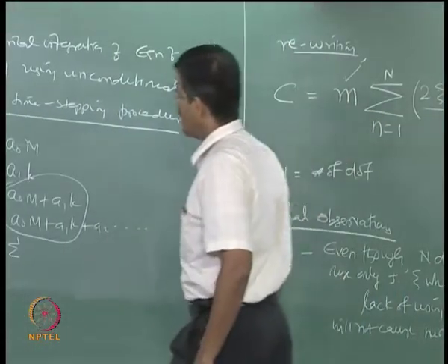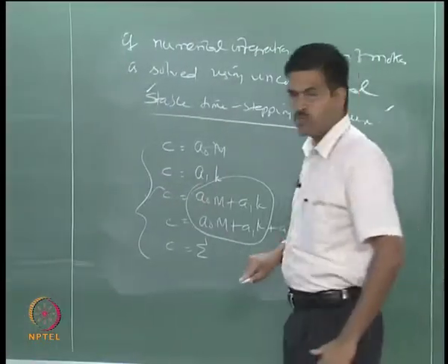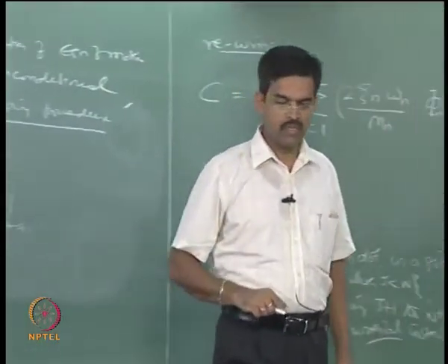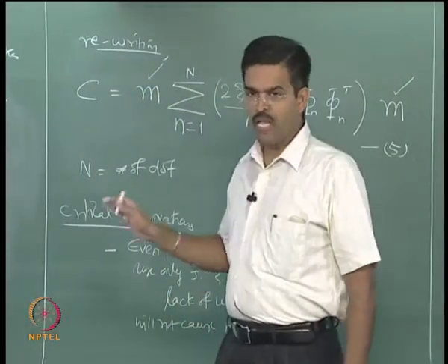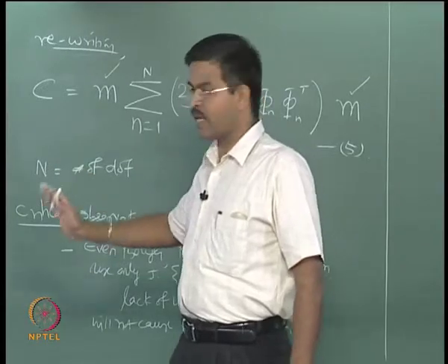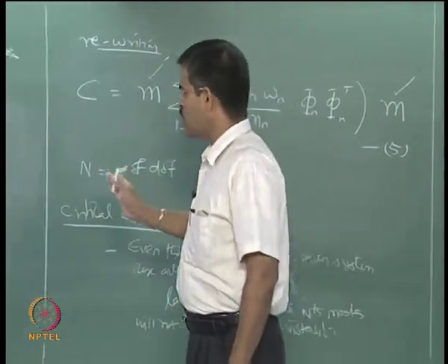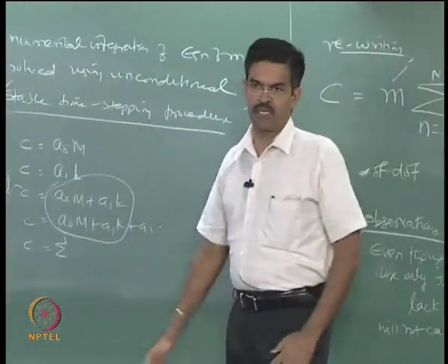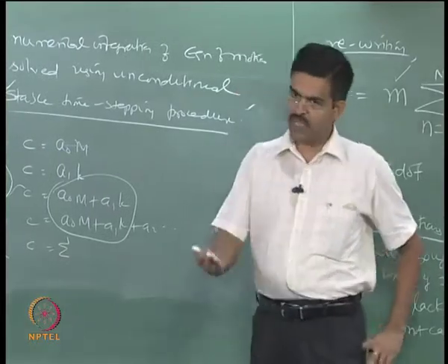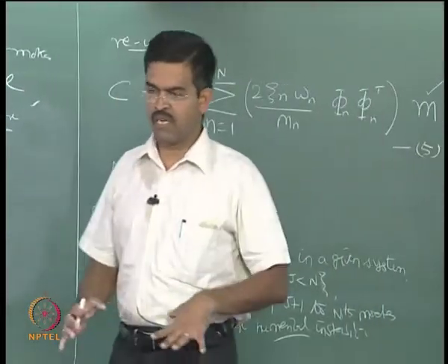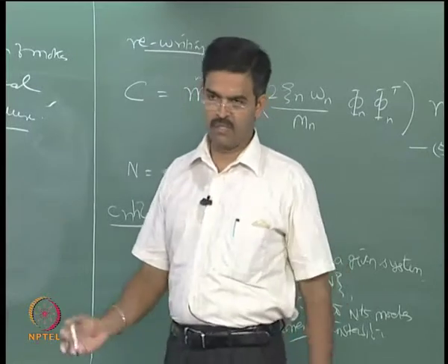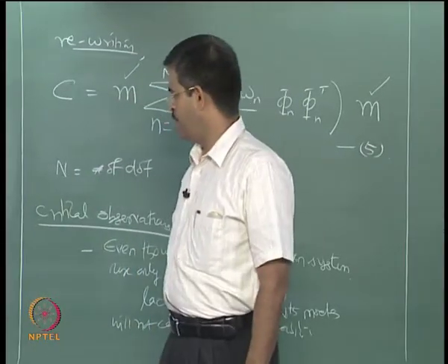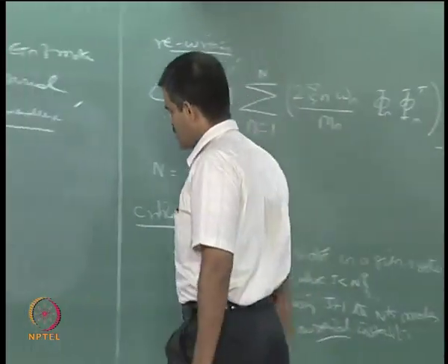Most practically, Rayleigh damping is employed for offshore structures where FSI is involved, because the damping values you get by applying the Rayleigh procedure are closely similar to what you get by experimental techniques in aerodynamic damping. That is what people have seen. Okay. There are references given in the literature, I will project them later in the second half of the lecture today. So, people say that yes, let us use Rayleigh damping.